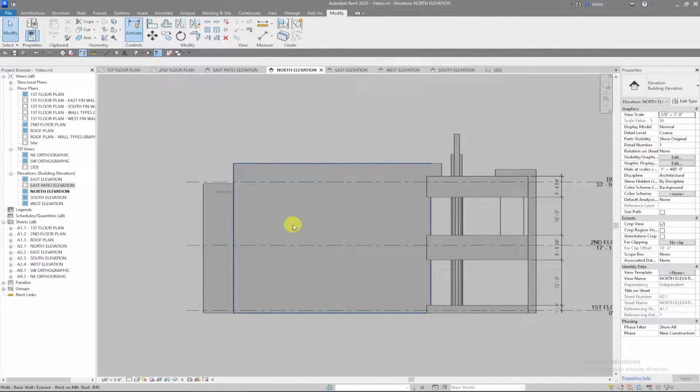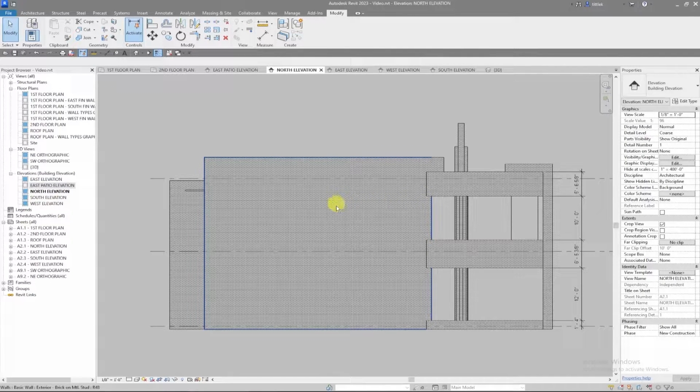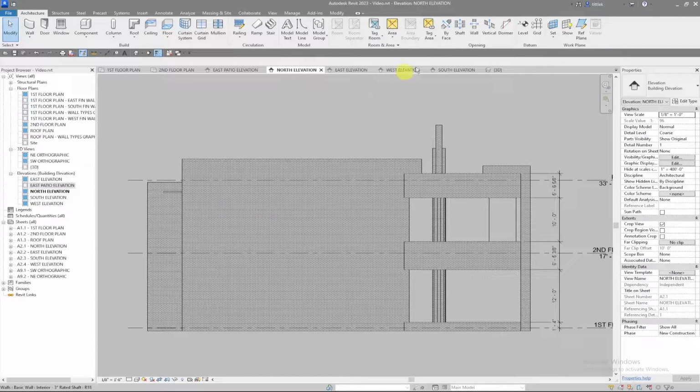So for this north elevation, and actually we have some on this east elevation over here, we have some punched windows. Now we could split this up horizontally and then vertically, but for the punched windows, there's 3 right here. So what I'm going to do is go to the architecture ribbon, and we have this wall opening button, which is great for creating an opening in a wall. This wall opening works very well with this punch window vocabulary. For the ribbon windows, these strip windows, that split tool works well, but for these punch windows, the wall opening works much better.